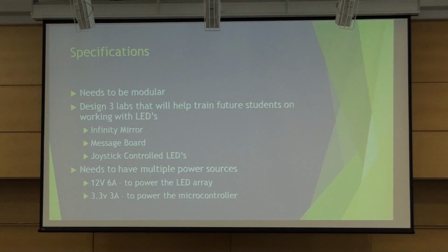A couple specifications that I had at the beginning of this project was that it needed to be modular. I needed to design at least 3 labs that will help train future students in working with these LEDs. The 3 labs being an infinity mirror, a message board, and a joystick-controlled LED array. It needs to also have multiple power sources, the first one being a 12-volt 6 amp to power the LED array. The second being 3.3 volt 3 amp to power the microcontroller and the joystick.